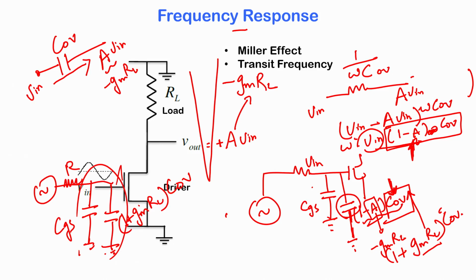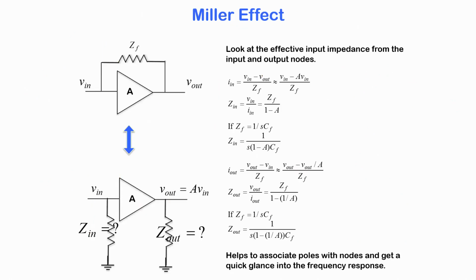Okay. So, there are many ways you can make use of the Miller effect also. You can artificially create a pole, so as to say, to stabilize amplifiers, etc. But nevertheless, this is a problem that you must be aware of. And it is not only true for MOSFET circuits or MOS capacitors. So, here I have given you a slide where any amplifier with any feedback impedance across it will experience this equivalent of a Miller effect. So, if you have the time, do go through these arguments, although I will not discuss it right now.